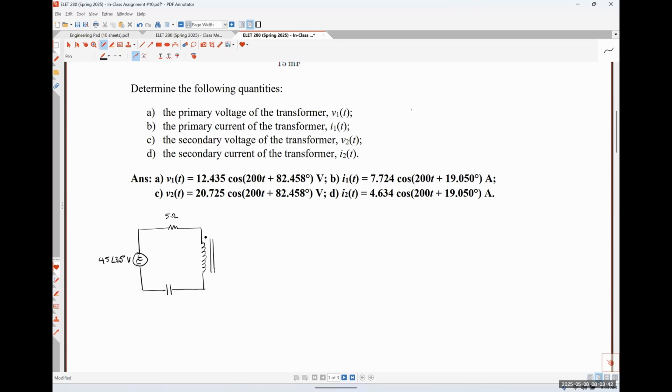So the impedance of a capacitor, ZC, is given by 1 over J omega C. The 2 pi thing that you're talking about is when you're given the linear frequency, but we were given angular frequency here, so we don't need to have that factor of 2 pi. It's already built in. Okay.